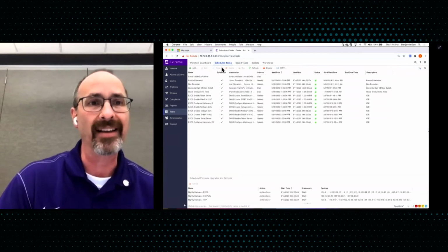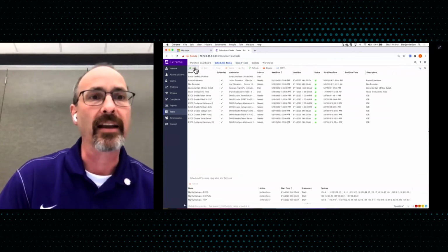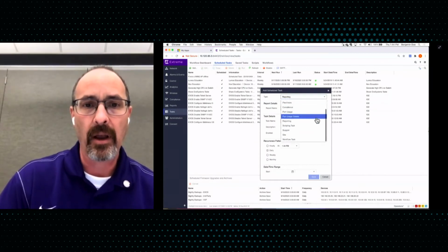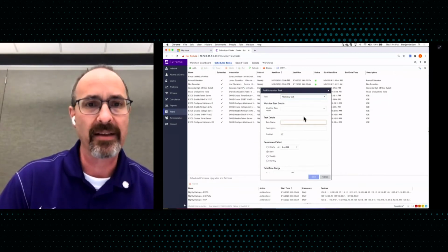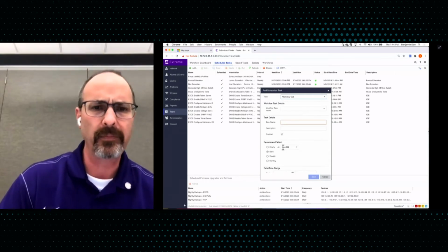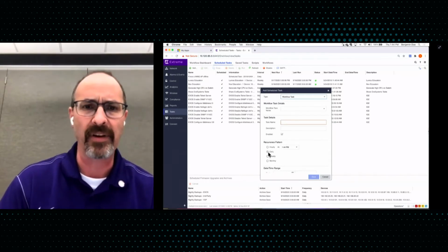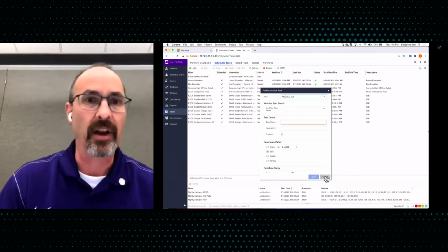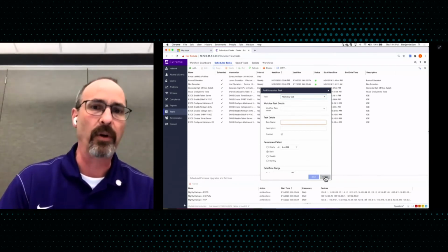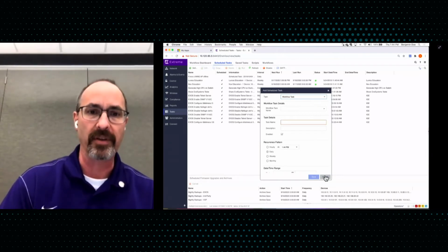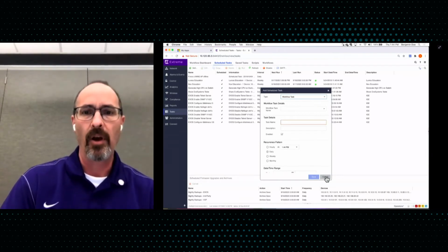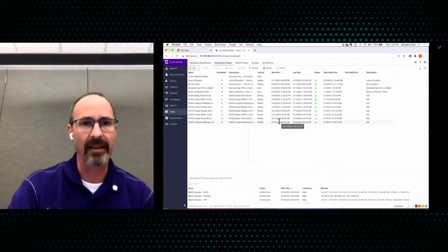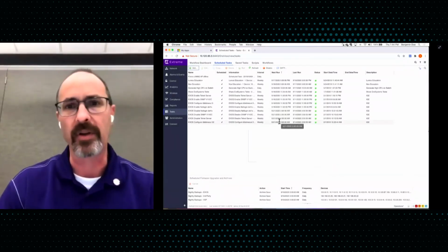then we could have come over here and hit Schedule Tasks. I can hit the Add button here just to show you really quick. I can come down and say Workflow Task. I could have chosen that workflow. I could say run this every day at 5 p.m. or something like that. And that would have accomplished it. So now you've launched it, one of the 3 ways you can launch a workflow, which is scheduling, manual, or via an alarm. So I think we handled that particular question.